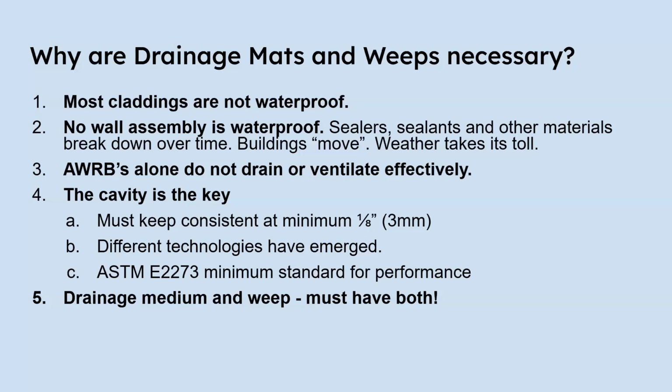And in many cases, you'll see that gap widen to 6 millimeters or 10 millimeters, depending on the type of cladding used and the necessities to ventilate perhaps more effectively. The wider the gap, the more ventilation takes place. And ventilation is obviously a key element in drying out the wall cavity itself.